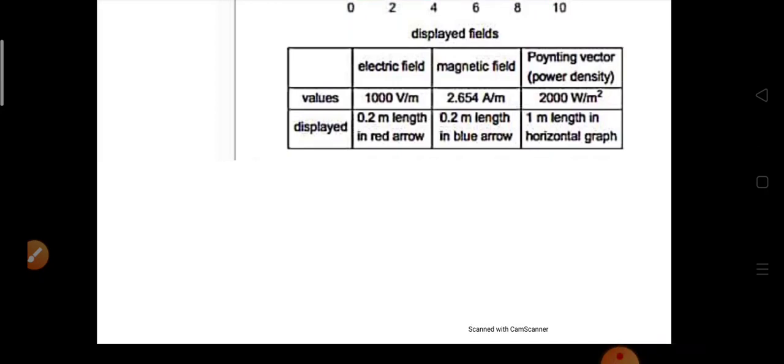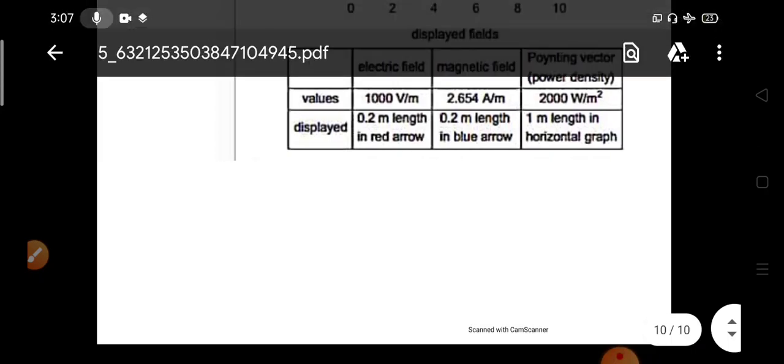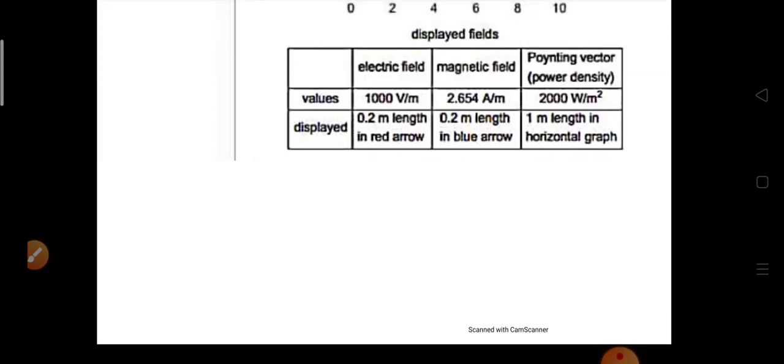However, even in the guided case, there are certain occasions where you can have completely transverse electromagnetic waves, but due to the boundary conditions, that is, the reflections and multiple reflections at the boundary, we get transverse electric waves or transverse magnetic waves, depending on the incident polarization of the electric field or magnetic field.